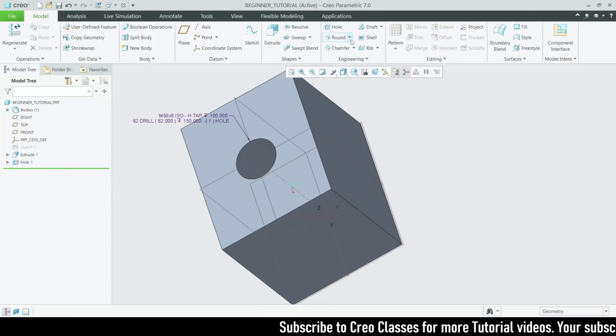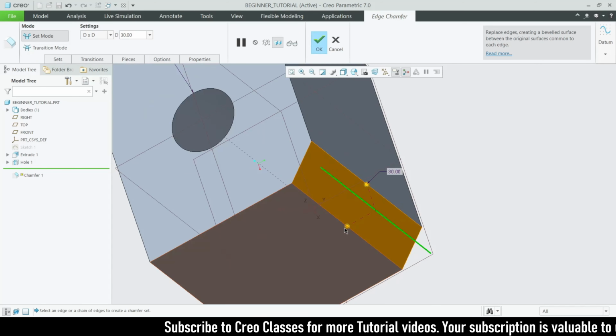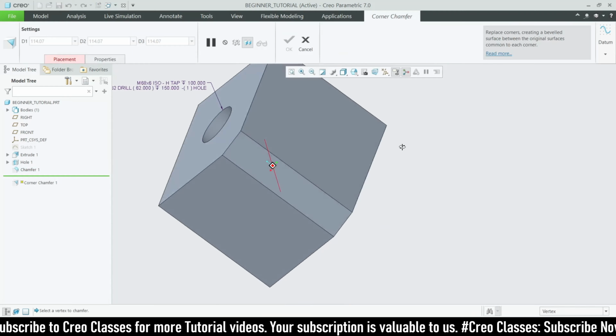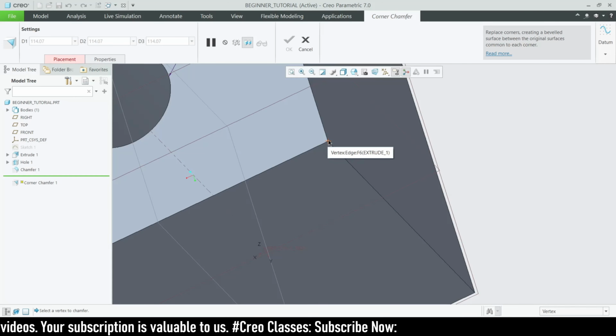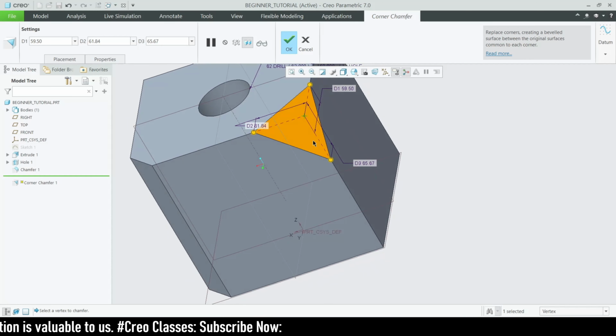So edge chamfer is nothing but this edge. If you select this edge, it will be chamfered for these two faces only. If you go for the corner chamfer, all three sides will be chamfered. For this, we can't select a line; we can select only the point. As you can see, it has been chamfered for all three sides.